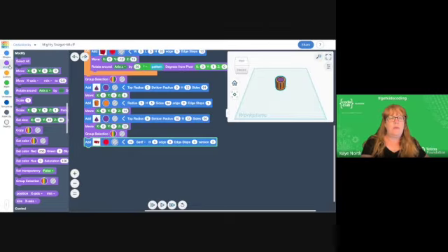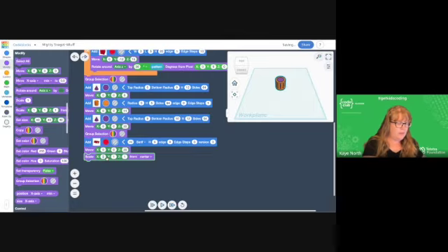So from the modify menu, let's grab a positioning button. We want Z to be at 29 because it's up the very top of our shape. Now we're going to drag across the scale. Our scale for X is 0.3. Our scale for Y, 0.3. And Z is 1 from the center. Finally, group that selection together so it becomes one shape.